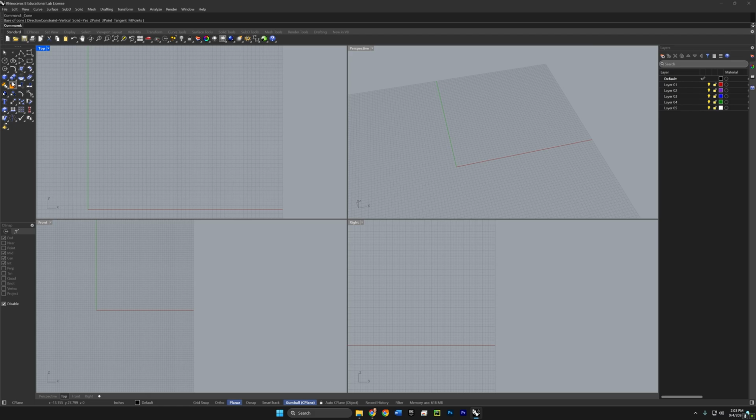Let's open up the solid creation panel by clicking on the triangle in the lower right, and then we'll just bring this open to dock it. And notice that if we click the cone button to create a cone and we move into the perspective window, the icon in the top left corner turns blue. That's Rhino's way of telling us that the perspective window is now active.